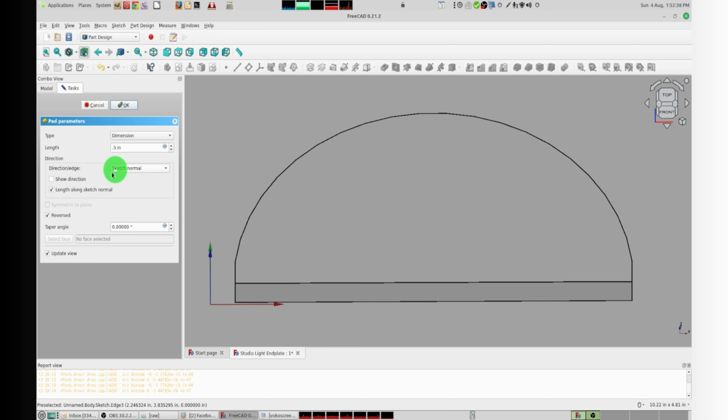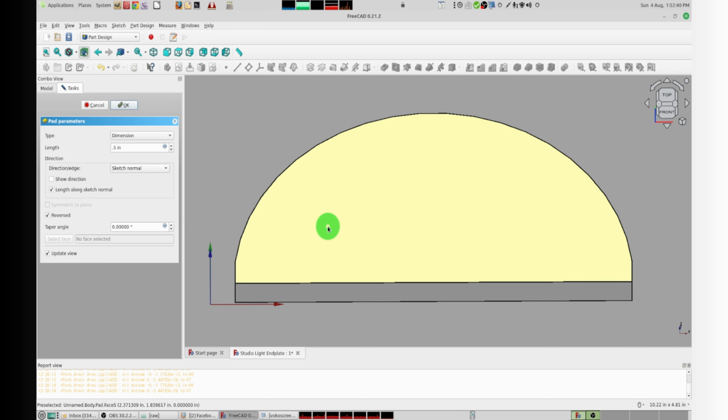Now you'll notice that I set it to reverse. This is because I like the top surface of my project to be 0 on my CNC machine. It just makes it so much easier for this muddled mind to figure out when working with depths and so on.